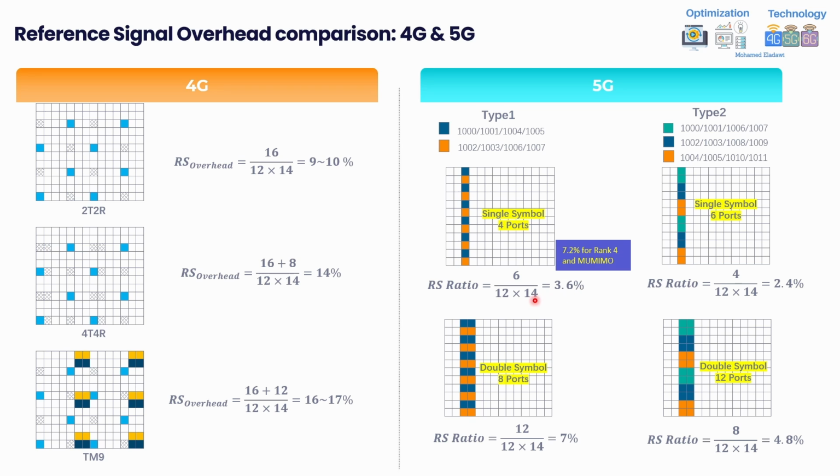Second point about this part. Here I mentioned that the cell-specific reference signal is being transmitted over the entire bandwidth. Here this is not the case. The PDSCH DMRS is associated with the number of resource blocks used by PDSCH, because DMRS always comes with PDSCH. So let's assume that you have only 10 resource blocks assigned to a single user. This means your DMRS will only be transmitted across those 10 resource blocks.